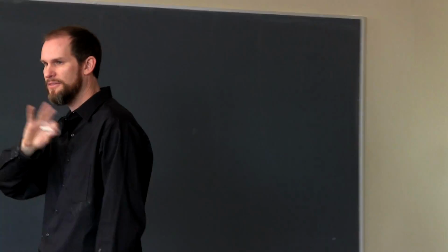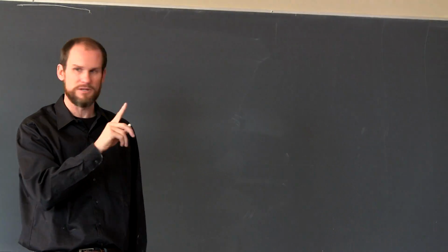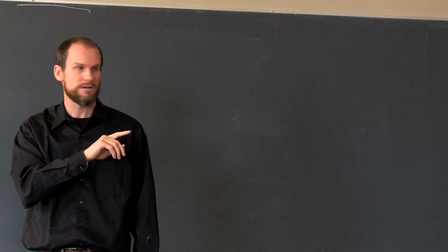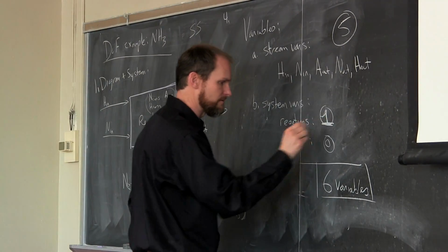Okay, so this is taking into account the consumption and the generation and the reaction stoichiometry to get 1 degree of freedom. We'll do all the math to get more rigorous with this next chapter. For now, make sure you count 1 degree of freedom per reaction.